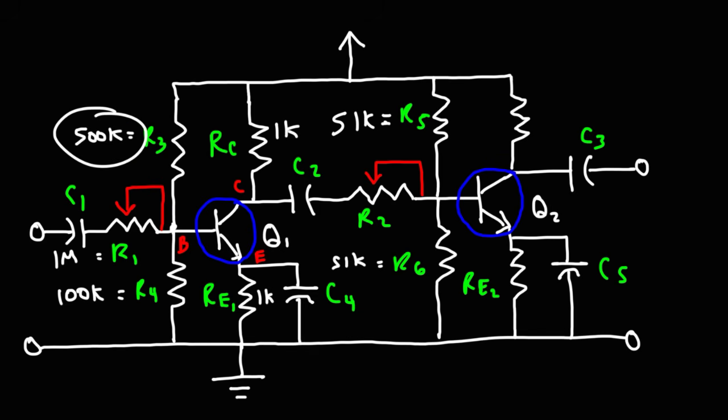Here I didn't do that because it really wasn't necessary, because the input voltage here will be very, very low. But now the voltage at the second stage will be higher. So I want Vb to be higher. That is the potential at the base. Because if Vb is too low, then a high input voltage could drive it to cutoff or saturation. Now let's say that our collector supply voltage is 12 volts.